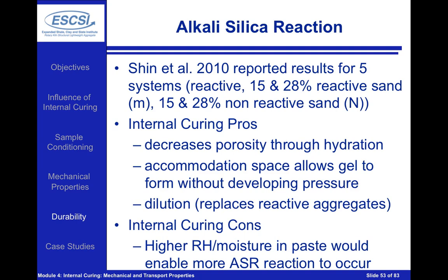Shin reported results for several different systems here, looking at reactive sands at a 15 and 28% replacement level, and non-reactive sands at a 15 and 28% replacement level. Really the whole idea here was to look at some of the pros and cons. So the pro is that internal curing will decrease the porosity, which will make it harder for fluid to get into our concrete, and water is very important for the ASR reaction.